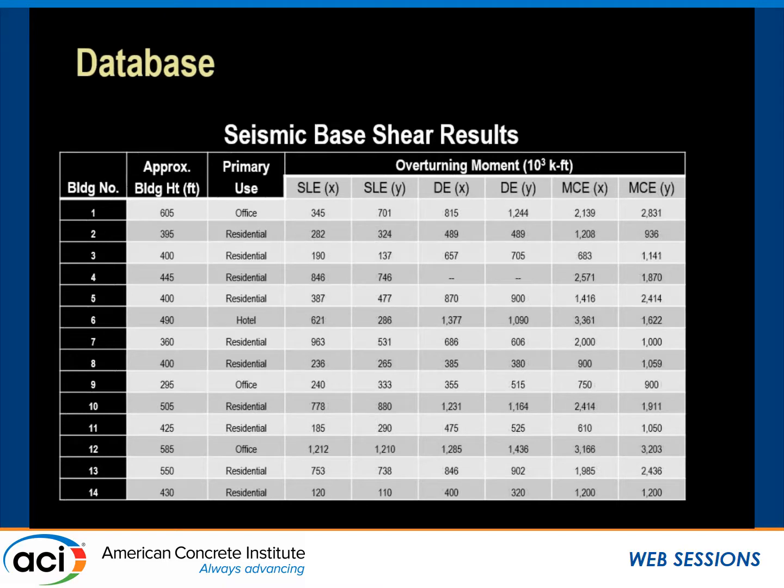Okay, similarly, this is overturning moment. This is not the right label. This is the right label, overturning moment. We collected the same exact results for the same buildings, just looking at the base moment, trying to glean any information we could about what that amplification factor would be. This is most important for proportioning your foundation system based on DE or SLE demands.